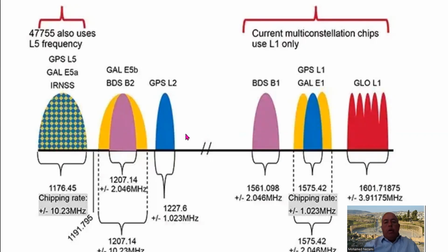The thing also to recognize is that we've got different waveforms. Most of the waveforms are based on basically code division multiplexing or chipping, and they're basically QPSK or BPSK shaped. I know the US is putting a system out that uses a continuous phase modulation system. That's still experimental work, which is a more efficient waveform and enables the devices to give you more accuracy. But you can see the bandwidth.